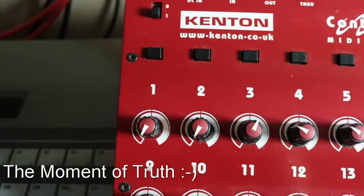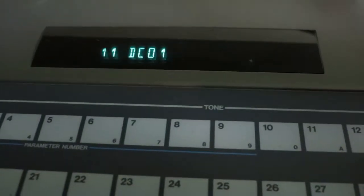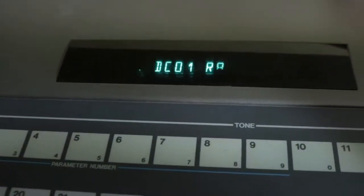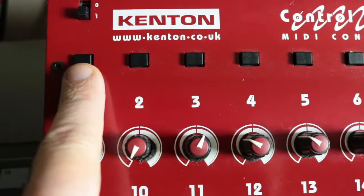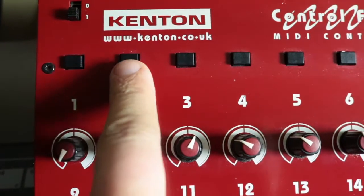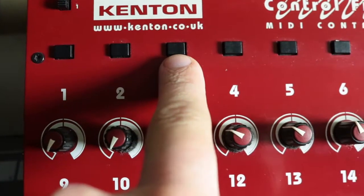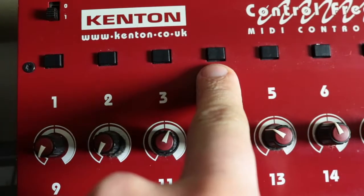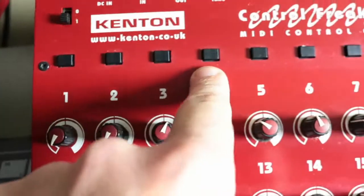Right, so now hopefully if I press button number 2, there it goes to 8 foot range. If I press button number 1, it goes to 16 foot range, and then you can carry that on. So we're sending 0 data from there, then we're sending 50 from there. If we go to something like 120 or something, we'll probably get it to 4 foot, and if we send the 255 from button number 4, we'll get it to go to the 2 foot range.